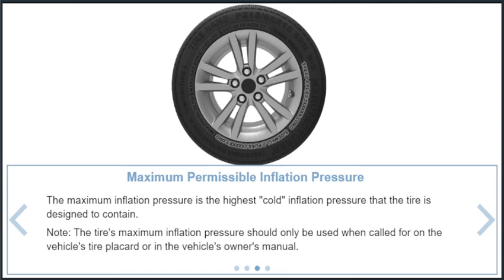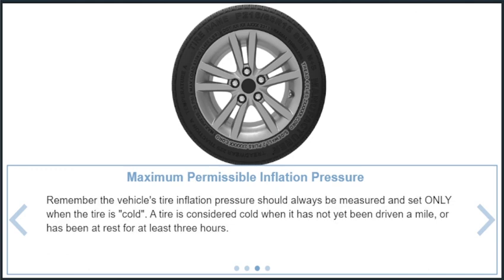Note, the tire's maximum inflation pressure should only be used when called for on the vehicle's tire placard or in the vehicle's owner's manual. Remember, the vehicle's tire inflation pressure should always be measured and set only when the tire is cold. A tire is considered cold when it has not yet been driven a mile or has been at rest for at least 3 hours.